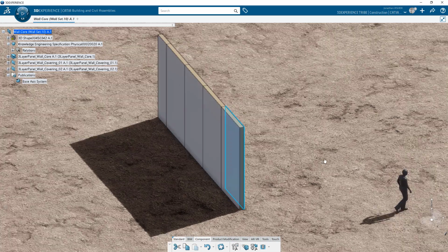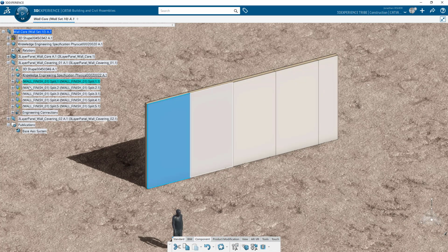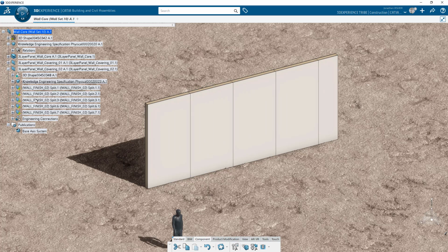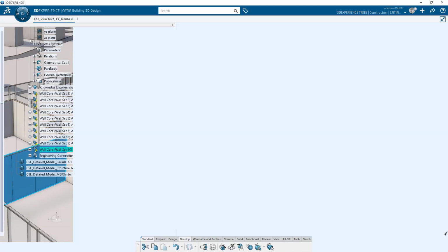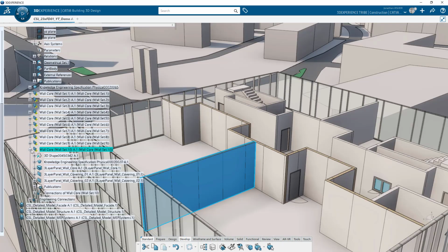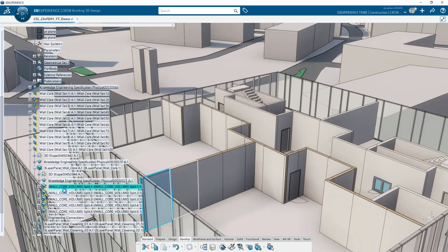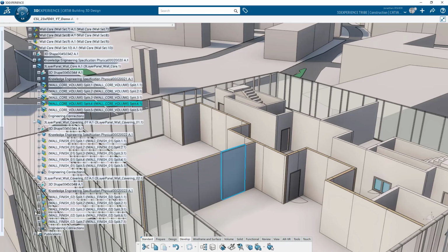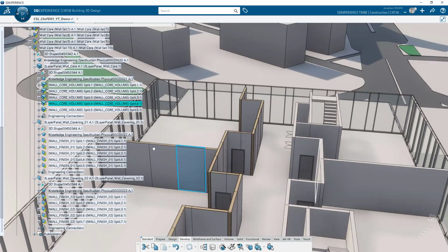So take note, the multi-split actually outputs specifications for component-based design. So you could attach object types that contain engineering templates to the specifications of multi-split, and using change LOD instantiate those engineering templates automatically. In practice, you're nesting object types inside of the other and using change LOD to automatically instantiate those engineering templates daisy-chained one after the other.